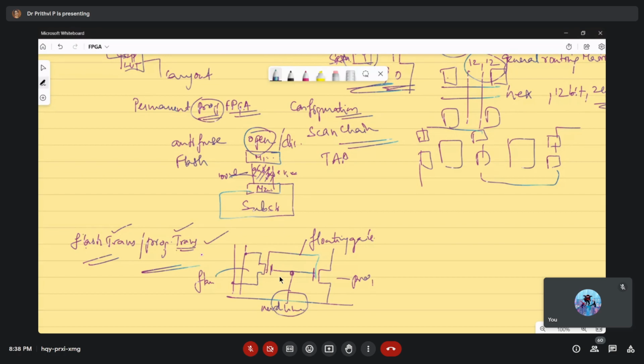Okay, so when we are taking these logic blocks, how they are developed or how they are able to implement the logic is simple mux format only. Any level of mux you take, if more inputs are there, the mux lines will be increased. Say if 2 lines are there, we take 2:1. If 4 lines are there, we take 4:1, or 2:1 you can take. That sort of logic will be taken for muxing, or selecting or transferring the inputs to multiple stages.